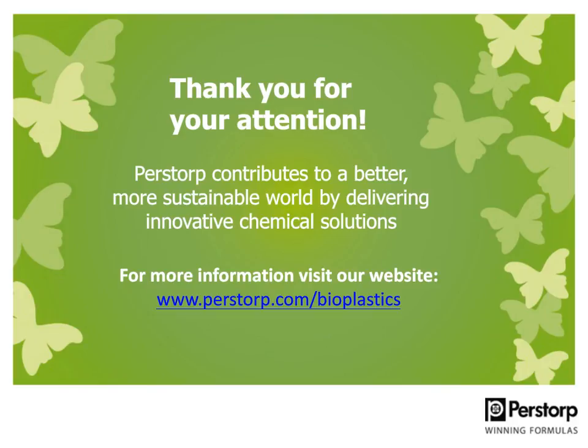And generally, when adding PCL into your formulations, we suggest that you start with the recommended processing settings, for example, PLA or the starch, and then incorporate the PCL. And you just have to be careful with the dosing so it doesn't clog the hopper or melt when you're feeding it into your compound. But in most cases, PCL will be the more stable component in these applications. And so start with the settings for the main matrix, the TPS or the PLA, or the most sensitive components in your formulation.